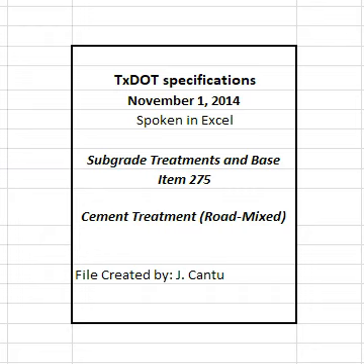4.3.1 Dry placement. Before applying cement, bring the prepared roadway to approximately optimum moisture content. When necessary, sprinkle in accordance with Item 204, Sprinkling. Distribute the required quantity of dry cement with approved equipment. Minimize dust and scattering of cement by wind. Do not apply cement when wind conditions, in the opinion of the engineer, cause blowing cement to become dangerous to traffic or objectionable to adjacent property owners.